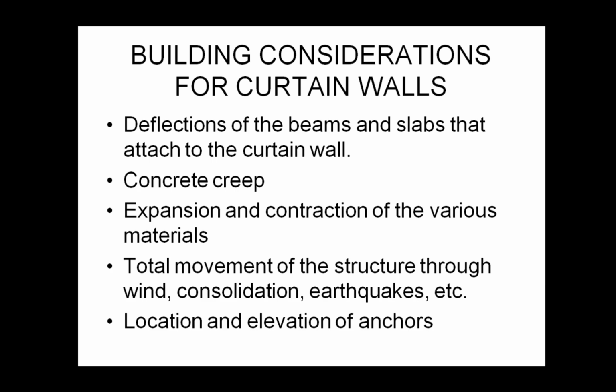Concrete creep. Again, you need to know all of the details of what you're building. There could be expansion and contraction, so that's why you have that kind of gap between the sections there, as well as total movement of the structure. You want to know how much is going to move from wind and seismically. Designed for the max, so that even if you get that maximum movement, your connections and spacings are right, so that your exterior isn't falling off.